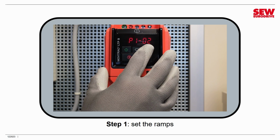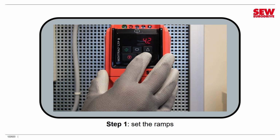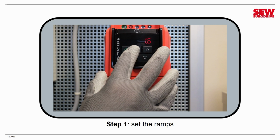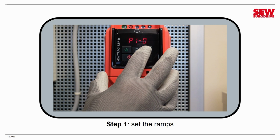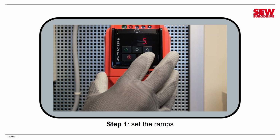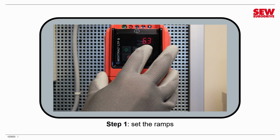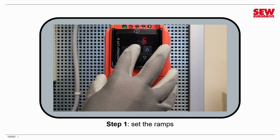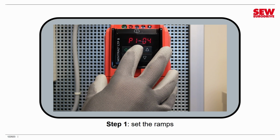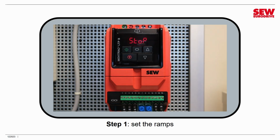Okay, now I navigate to parameter 3, and I hit navigate, and I enter my first ramp value, 1.6. Hit navigate. All right, now I go to parameter 1-04, that's the deceleration ramp. I hit navigate, and I enter my time, 6.7 seconds. I hit navigate again to accept it. And that's it. I've now programmed my ramps. I hold down navigate to exit parameter edit mode, and we're all set to test.